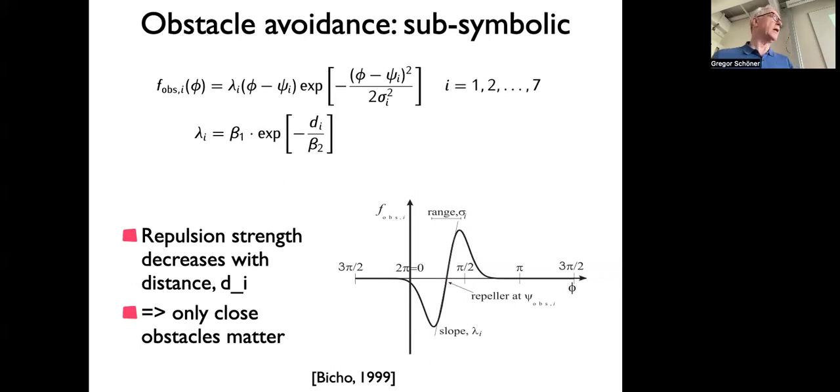We tried that out in the laboratory. That is somewhat limited. You can imagine this infrared light disperses too much, and there's not enough reflectors to get it. In practice, the kind of sensors we had, this depends on how much emission there is, was able to sense distances of about 50 centimeters max, maybe 40 centimeters. And the vehicle was about 35, 40 centimeters wide. And the one I'm talking about here, we have different versions of it. And so it would sense about one vehicle length.